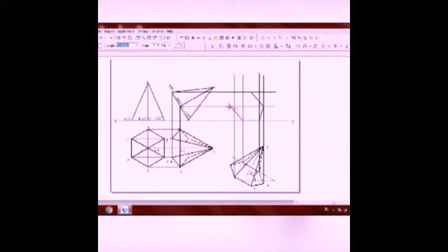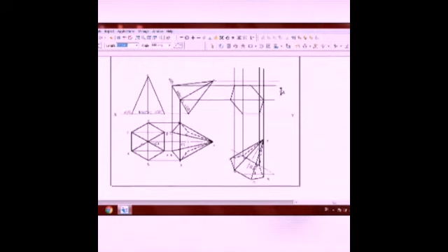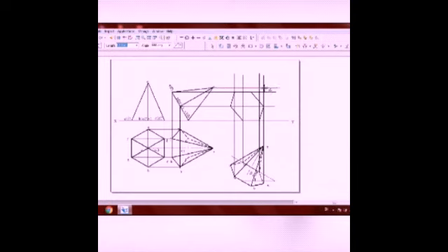One of the very important points that you have to note here is that the base is visible in the second front view. So all the lines of the base are not dotted. Now find the apex construction line from the previous front view, and it coincides with the already drawn line from the previous top view, and that is the apex. From there go to the 0.5 mm line option. From the apex join lines to all the base corners.